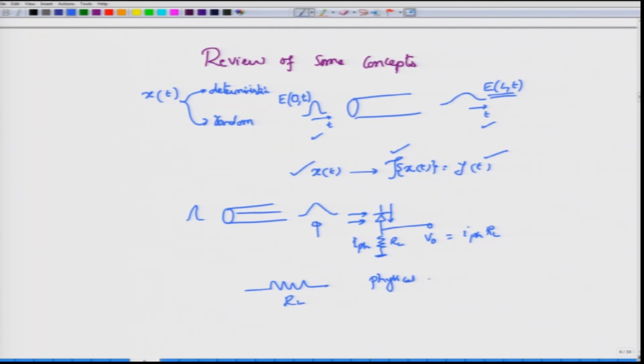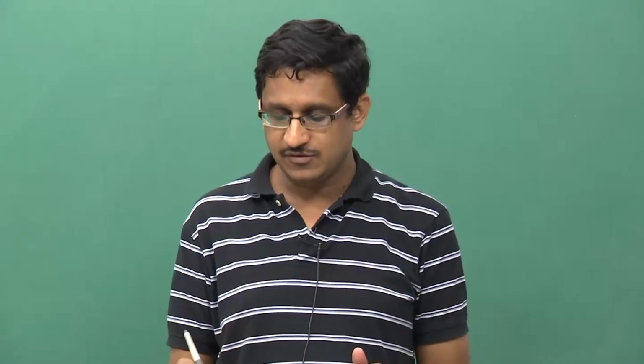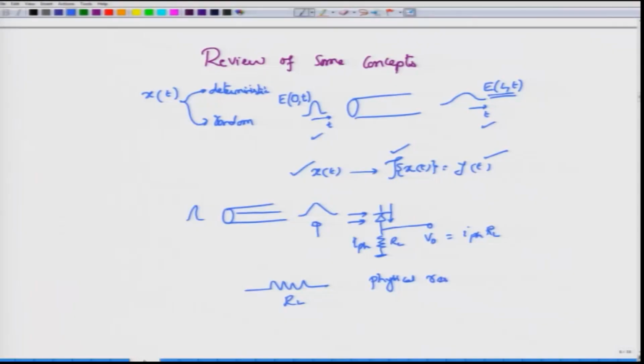It is made out of physical elements, atoms coming from whatever materials are used to make up a resistor, and because they are atoms and other things, they have some kinetic energy when the temperature T is greater than 0. One of the properties of these atoms and the electrons there is that if they have been given some amount of energy, then they would like to jump from the valence band into the conduction band.